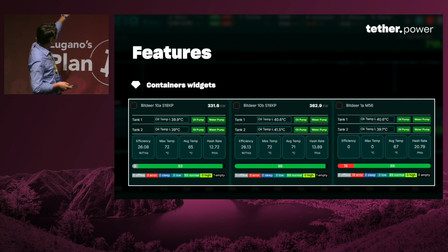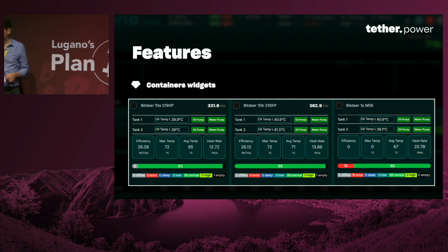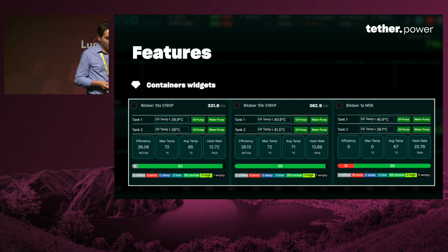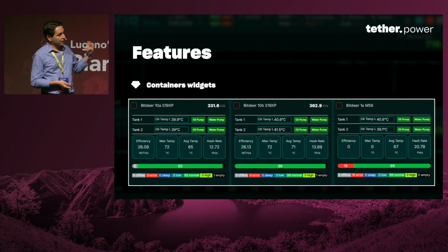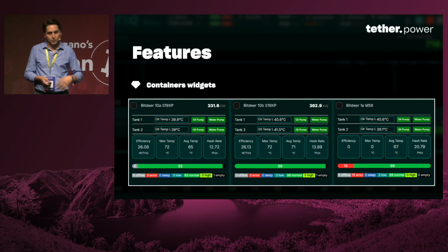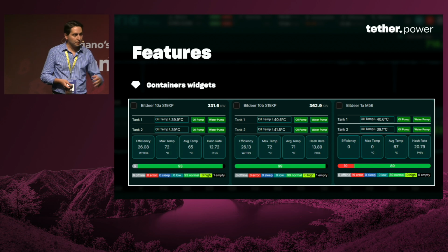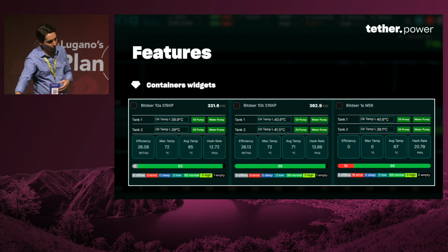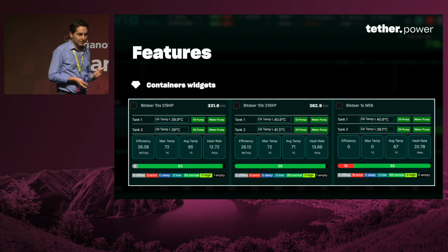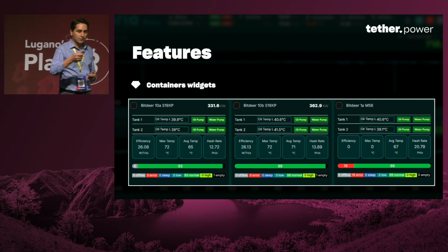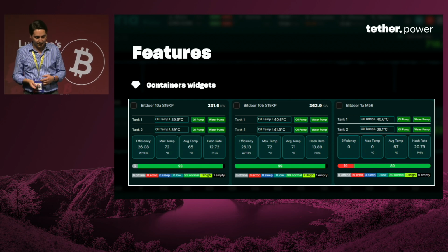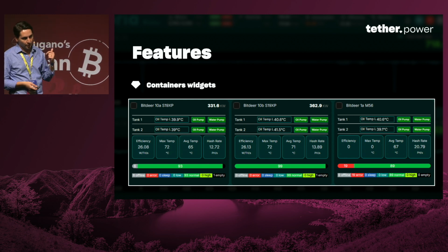And here, those temperatures that you see are what you're setting, the temperature that you allow. Again, these will change color. In this case, you see 39. Let's say it goes to 42, it turns orange. It goes to 45, it turns red. And then at some temperature, you have an alarm. And then you have the local alarm as well that basically just turns off the system. But this allows you to prevent that. You don't want to arrive at a situation where the local container management system is shutting down that operation. You want to see it here before, so you can intervene.